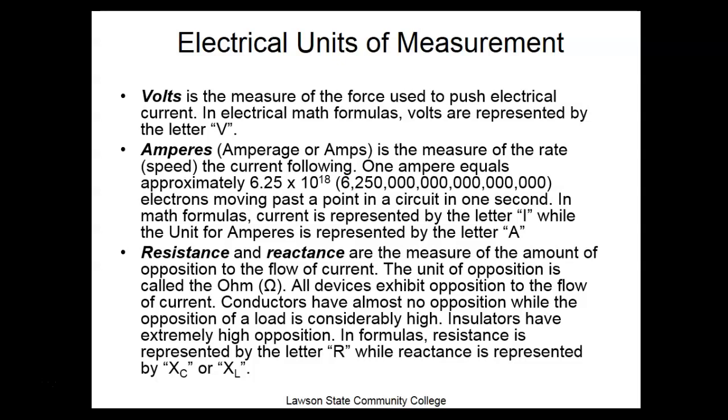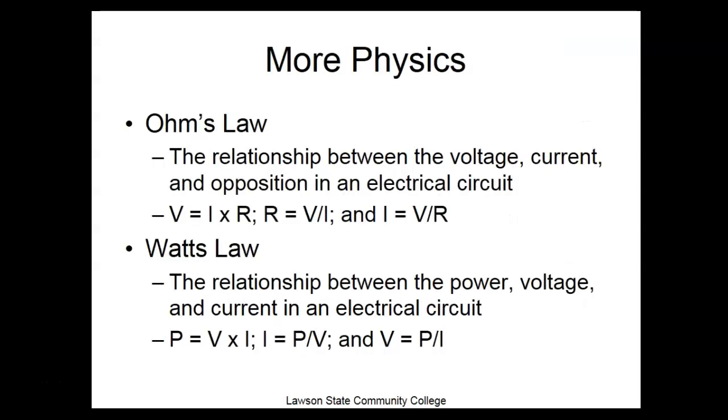So there's no such thing that has infinite ohms, even though when we put a meter on ohms and it comes up and says overload, it doesn't mean there's no resistance there. It just means the resistance is so high that your meter cannot measure it. We have a unit called a megger, which gives us the ability to actually measure the resistance of insulators. But it's so high that there's almost no ability for current to flow through them.